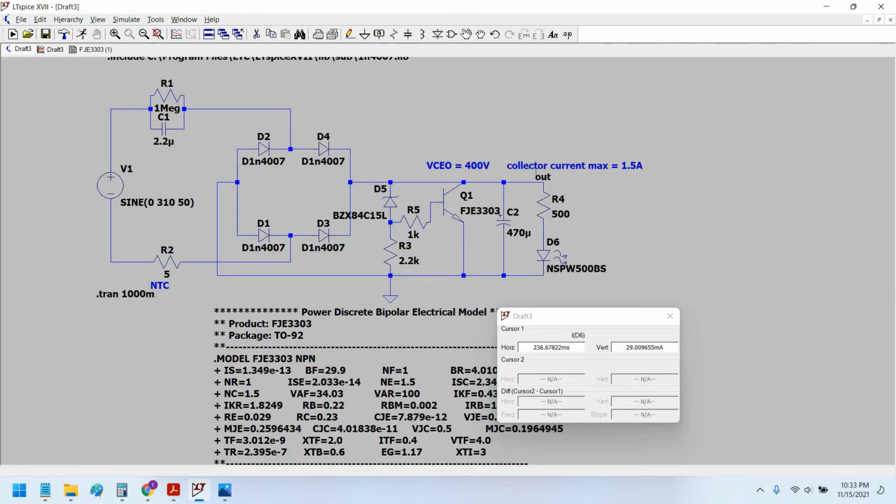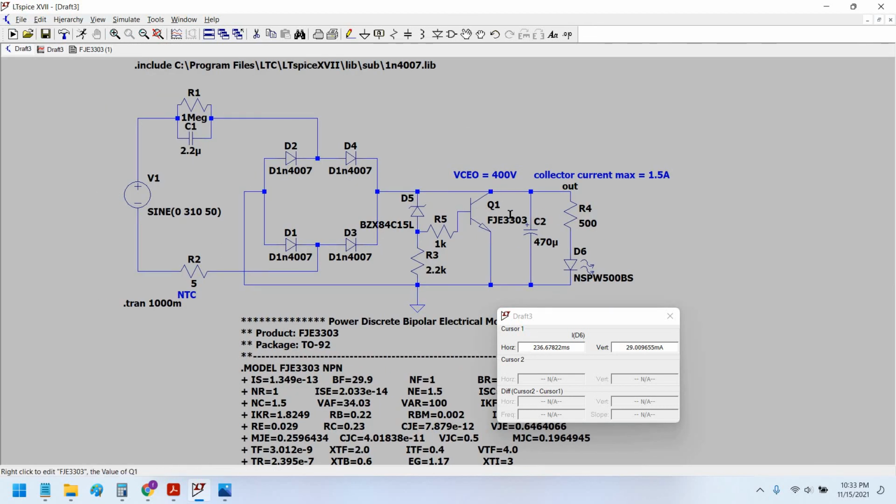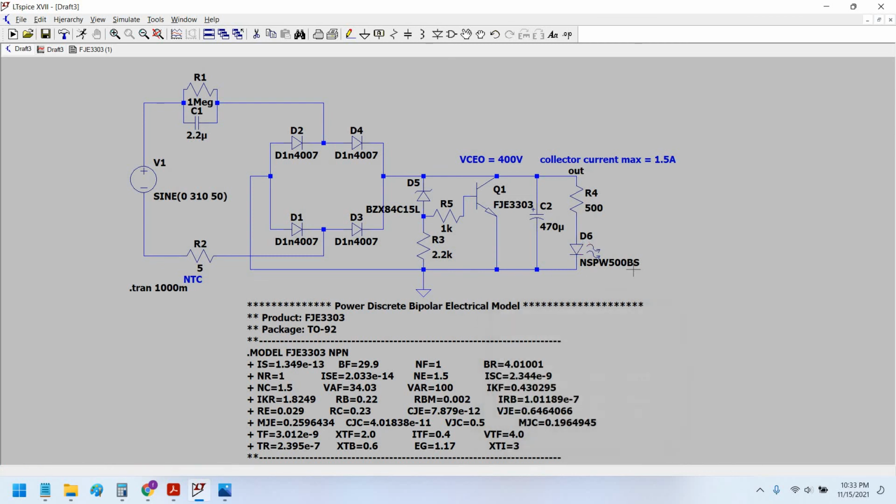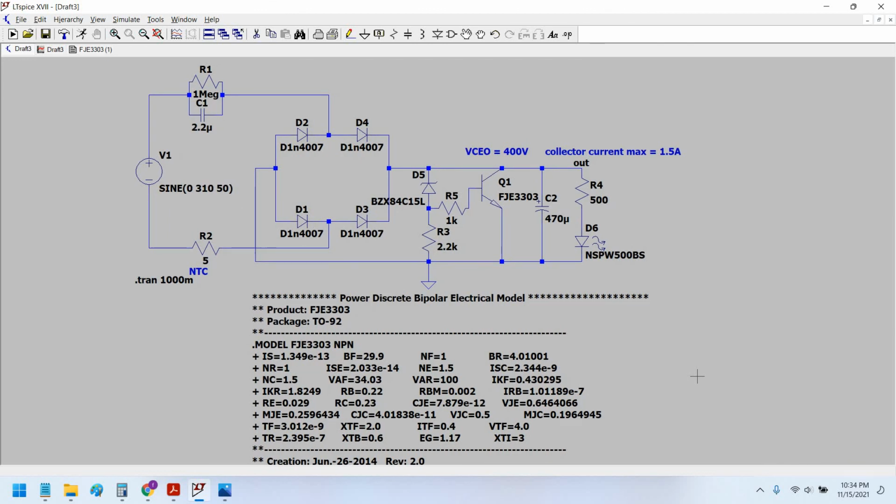So I'm trying to tell you that this circuit can deliver a current up to 140 milliampere, but we are not going to use such a high current because this is a single LED. If we use a series of LEDs and connect them together, that would become an LED string. In many commercial applications, you have seen high brightness LEDs and high brightness LED lamps for different ceremonies.